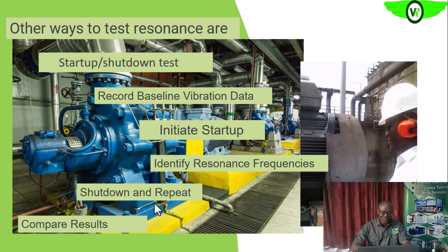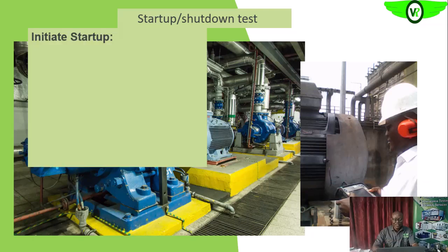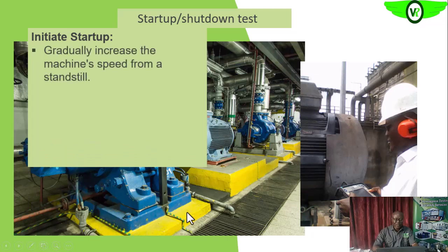Okay, then you compare the results that you have to draw your conclusion. So what do you do during the startup test? The first step is to initiate startup of the equipment. Then as you start up the equipment, you gradually increase the speed of the machine from that position of rest.